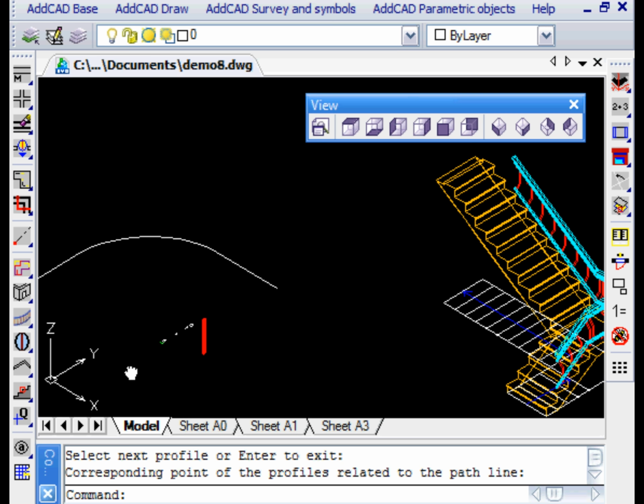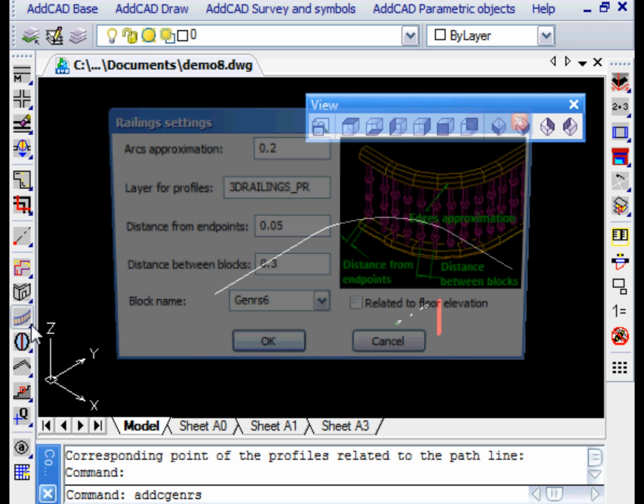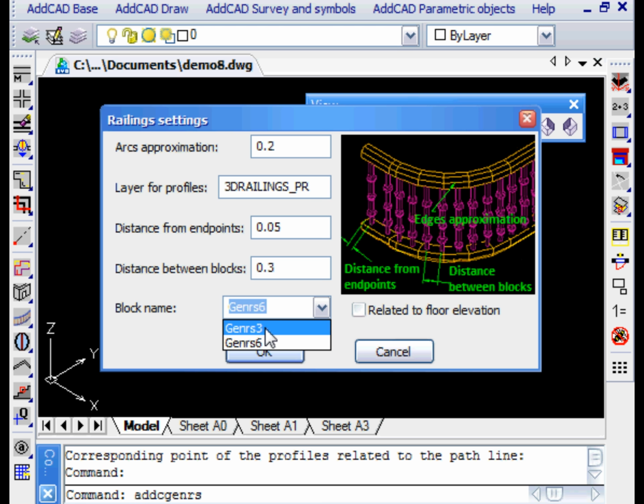As a last example, we want to create a fence. In the dialog box, we change the vertical element and assign a greater distance between them. To define the contour, we select the polyline in the drawing. Note that the polylines can also be of 3D type, freely drawn in space.